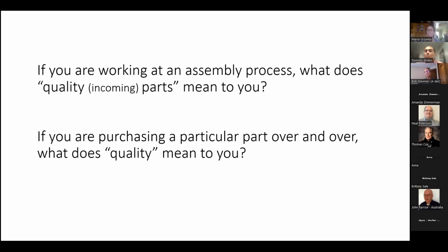It meets, it's ready to go to the next bucket of work. Okay. And if I told you, yes, and here's how you validate it, you put them together and you check that fit. If it's too tight, it's going to overheat. It's not going to work right. If it's too loose, it's going to feel kind of cheap to the customer. Here's about right. So if you were supposed to make parts that are just about right, make an assembly that's just about right, what are you going to ask for in the parts coming to you?